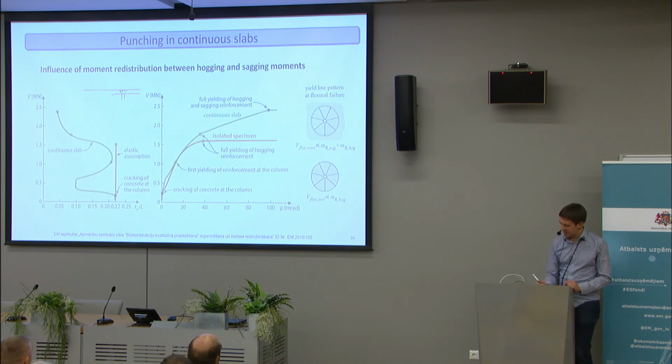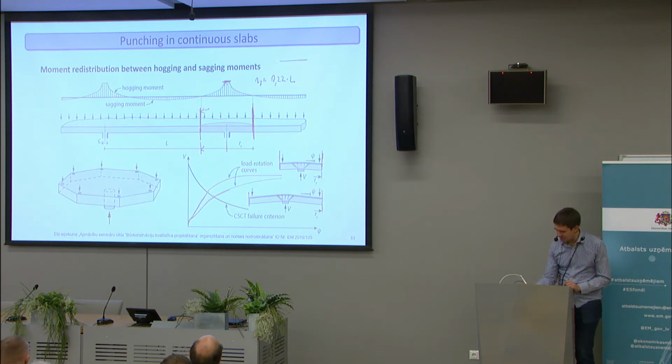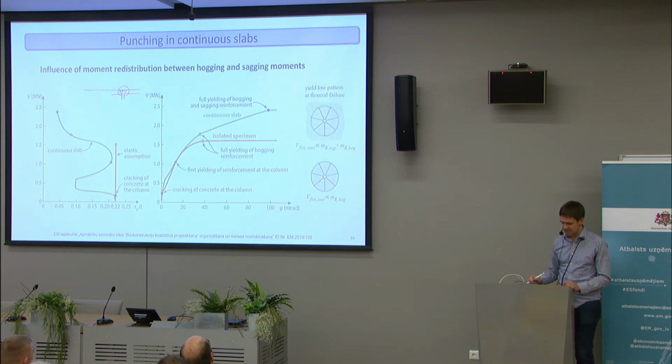The cracks form in here, and this area gets less stiff. So this means that the moments don't work anymore like a continuous beam like this, but a plastic hinge forms in here, and the moment starts increasing in midspan. So the line of moment contraflexion changes, it moves closer to the column.